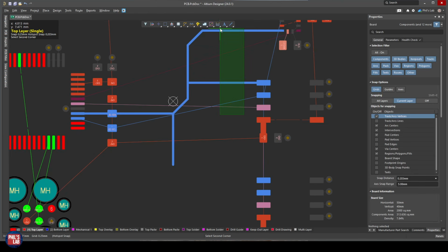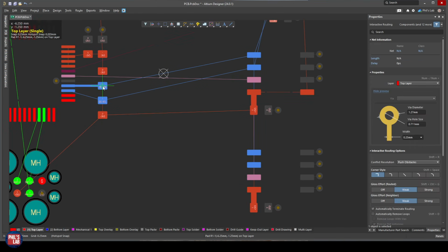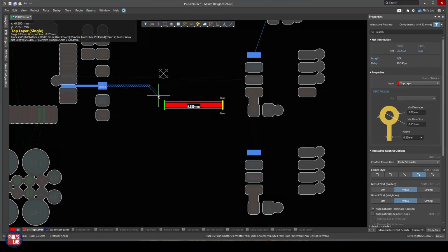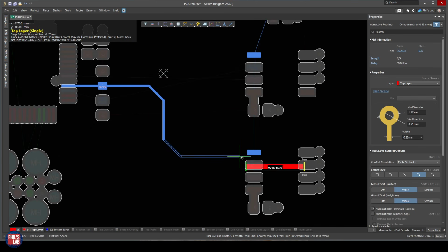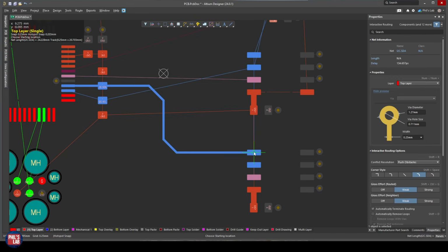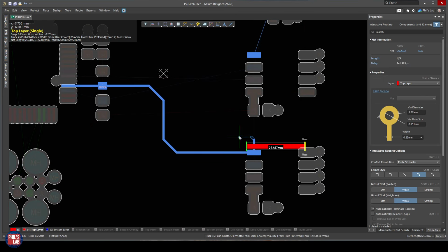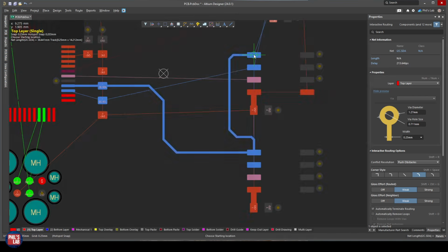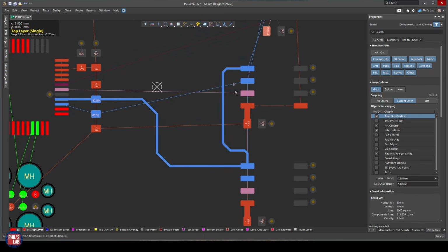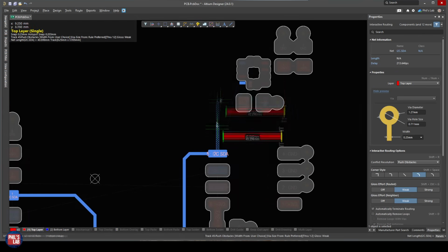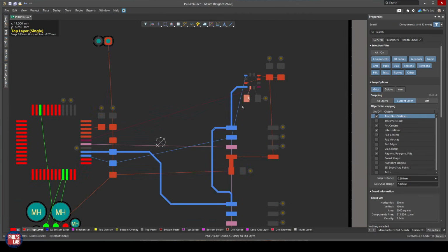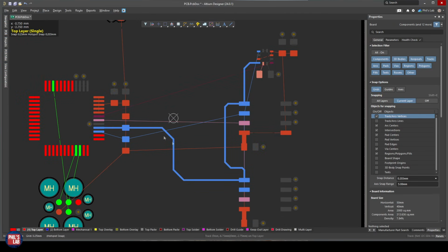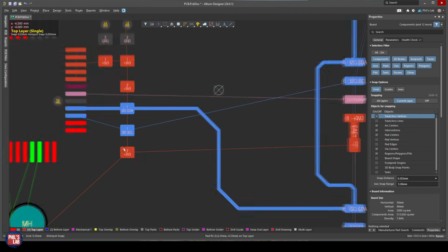Alternatively, if you don't like this branch topology, what we could do is kind of route through the components. So we start again from the host controller through the pull-up, and let's say we route down to the bottom EEPROM first, then we can come out of the bottom EEPROM and route into the top EEPROM like so. So we're following this path through the IC, so to speak, and out of the top EEPROM into the magnetometer. So rather than branches, we're routing through. So that is an option, of course, as well.